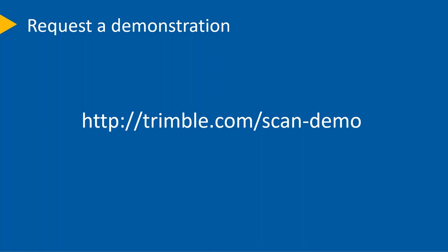TBC or Trimble RealWorks, what is better? So that's kind of a funny one. Trimble RealWorks will have a lot more inspection and modeling capabilities if you're trying to do analysis or BIM workflows. It's been around for a long time and has a lot of tools very specific to point clouds. TBC is a very strong geospatial software, so very good at putting data together in coordinates.